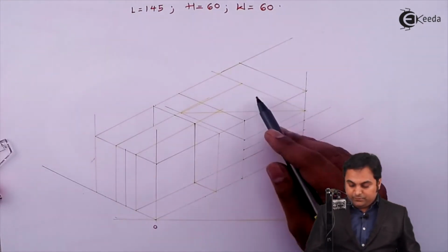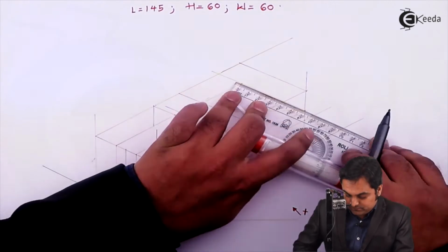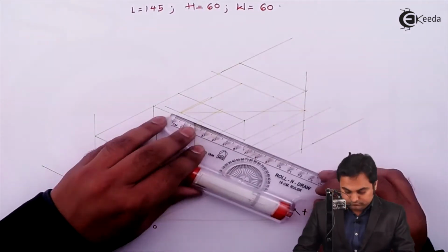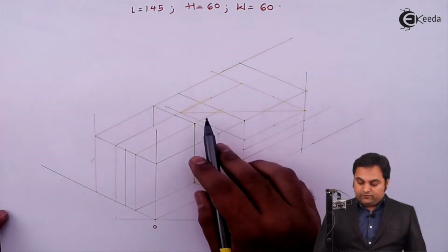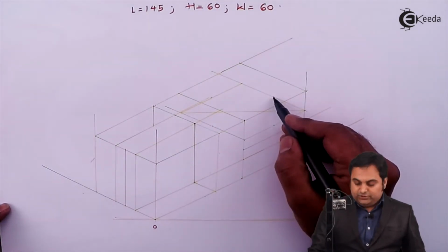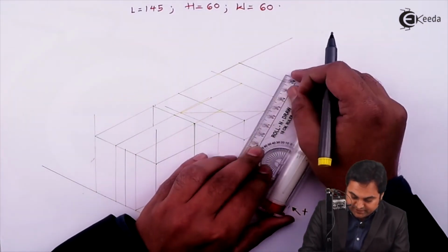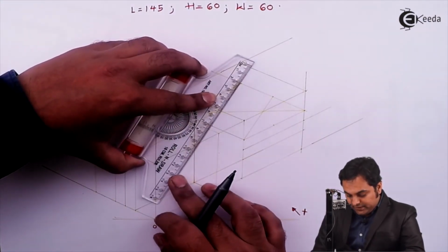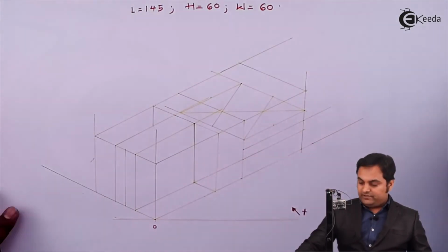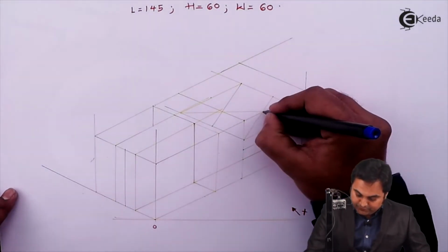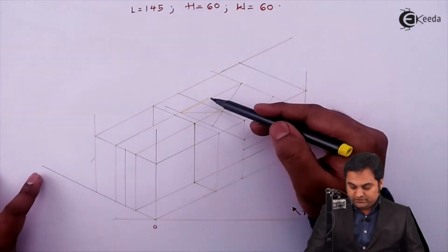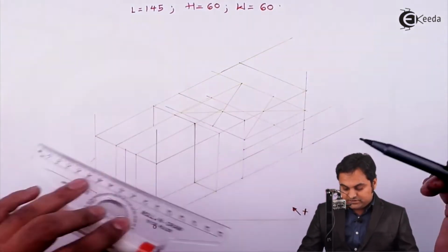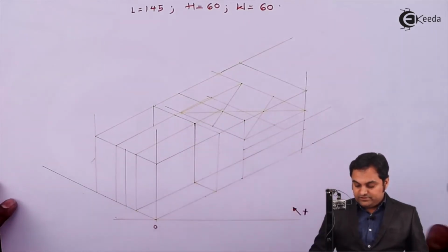Then marking the midpoints of each of the sides of the parallelogram. Next, after drawing the longer diagonal, the midpoint which is there at the top should be connected to the bottom corner, intersecting the diagonal. Bottom midpoint to the top corner, intersecting the diagonal. Now where the diagonals has been cut, here I am going to get these center points. Next, from this center to center, I'll draw light line, because the semicircle should end here between these limits.